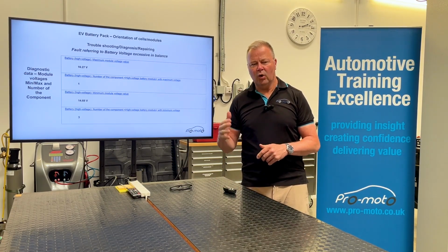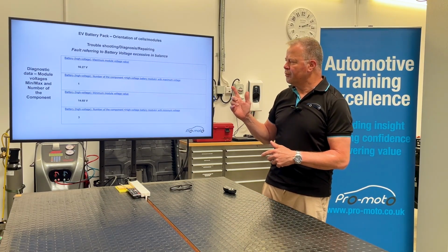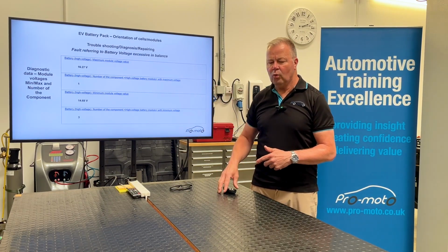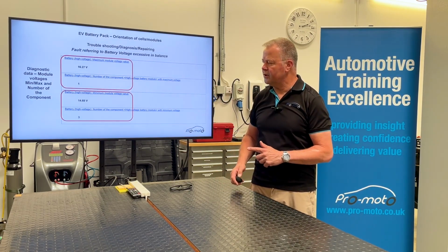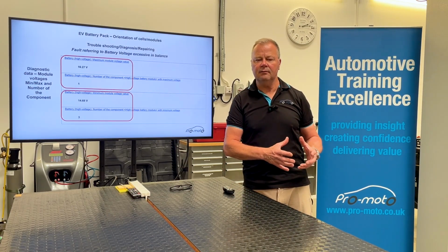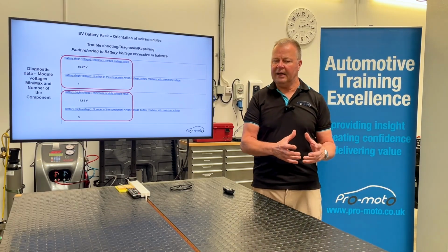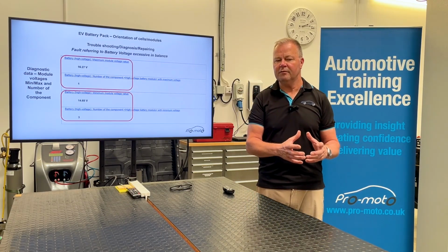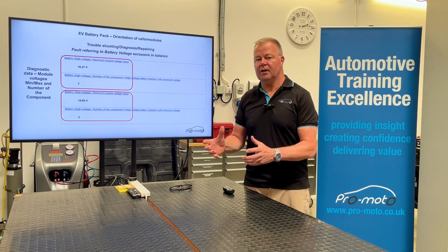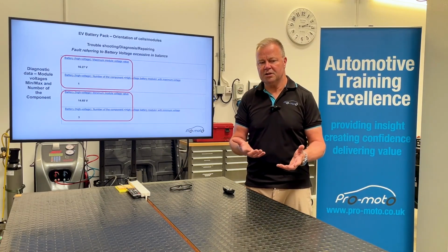We've identified from our data list modules 1 and 3 within the battery. I'll just highlight those for you so you can see. Now, for anybody that's done some electric vehicle training and understands a little bit about battery technology, you'll understand that battery imbalance is quite a significant problem for batteries. And in most cases, if the battery imbalance becomes significant enough, it can mean the battery will switch off. Hence, we have a non-start situation.